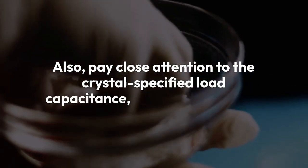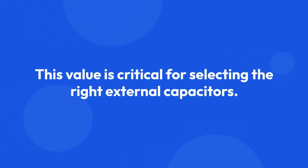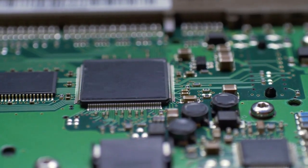Also, pay close attention to the crystal's specified load capacitance, often written as CL. This value is critical for selecting the right external capacitors. Most MCUs use fundamental mode crystals, not overtone types, so ensure you pick the correct one.